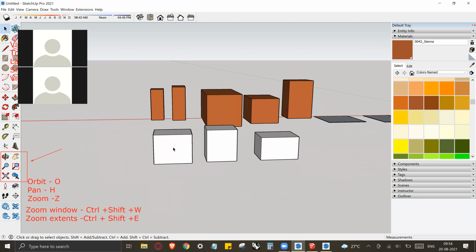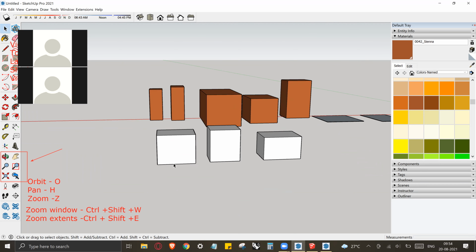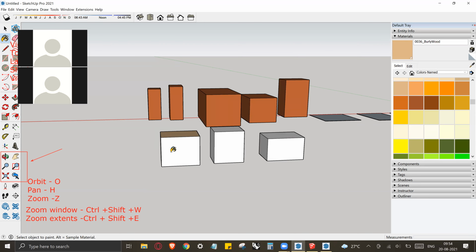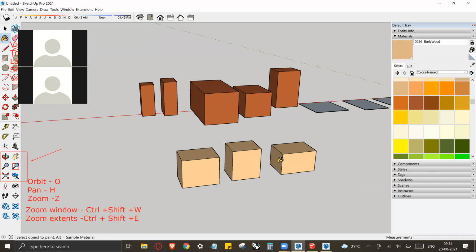For now, let's say that you have just made all these surfaces like this. You want to give it one particular color. All right, let's say we'll change the color here. Now you know that either you can apply it surface by surface, or you can do control to apply it to the surface. If not, guys, if you hold shift and then apply a color, you see every single object that is right next to it. Okay, that is the entire copied object of it. You see it has gone ahead and it has the color. Okay, so this way, when you've got a surface, you can either just apply it to that particular surface, hold control and apply it to the entire object, or hold shift if you want to apply it to everything in the closest vicinity. Okay, basically everything that looks like it will get applied with that same color.